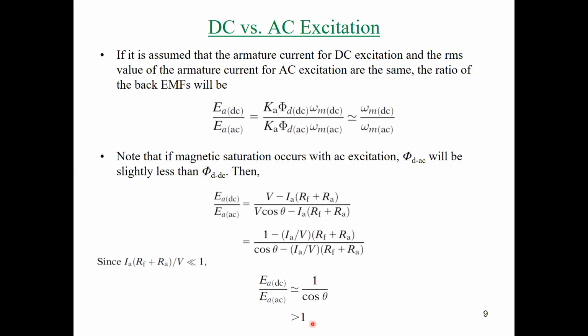DC. DC will have higher current. Why? Because there will be less impedance, because there will be no reactance in the circuit. Is it right? Yes. Reactance in DC steady state will be 0. So it's expected to have lower total impedance in case of DC, so you will have higher excitation in DC compared to AC source. This is expected in this kind of machine.